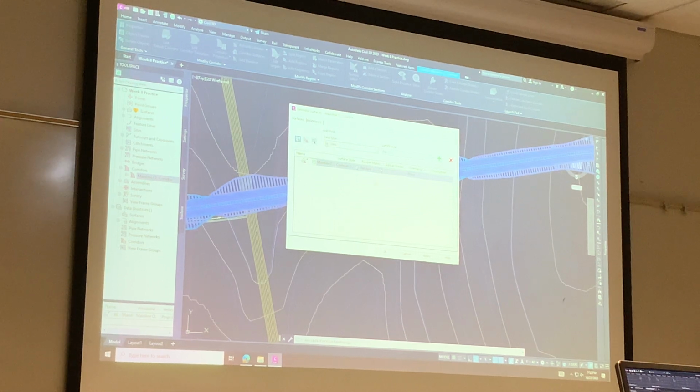So in order to insert data into this corridor surface, we're gonna select one of these options here under specify code. You'll see this is the add data section. We're just going to leave it as top because we want to get the entire top surface of this corridor. But if we wanted to specify, I want you to measure everything within or under this layer, then we could tell that as well.